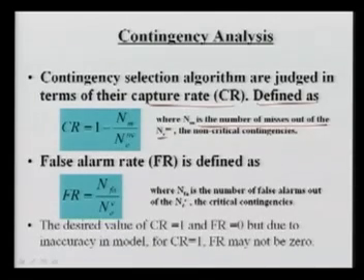As I said, suppose you are having 100 contingencies, and you have made a cutoff of 40, meaning PI more than that. Then 40 are critical and 60 you are saying are not critical. So in these non-critical contingencies, how many are the misses? How many critical contingencies give you NM?